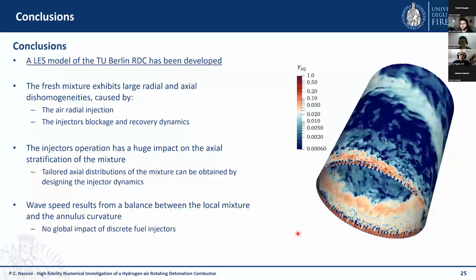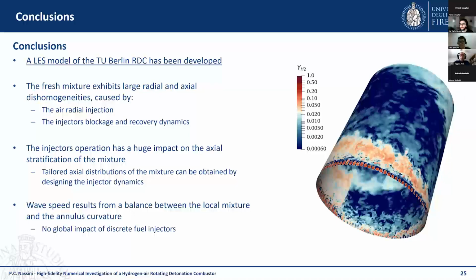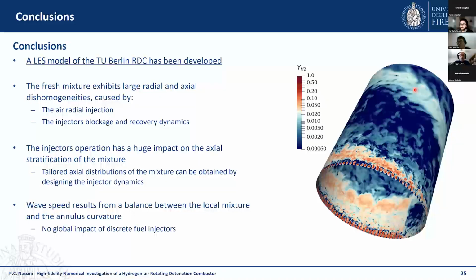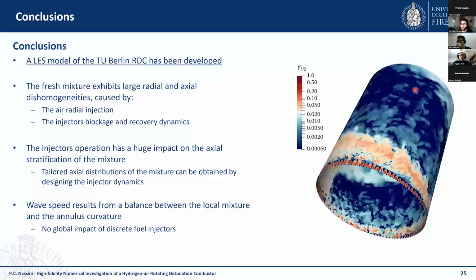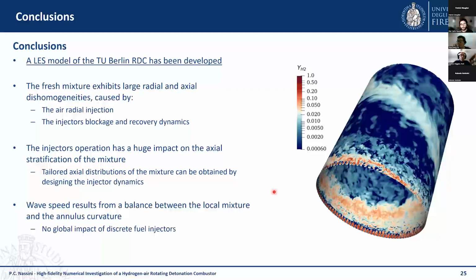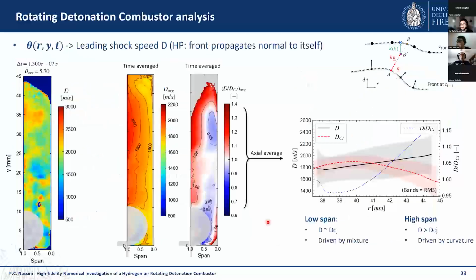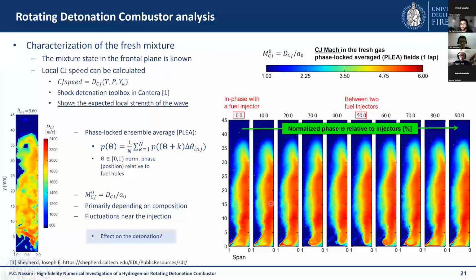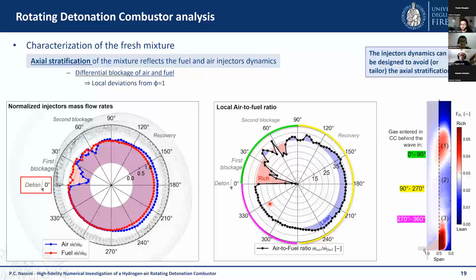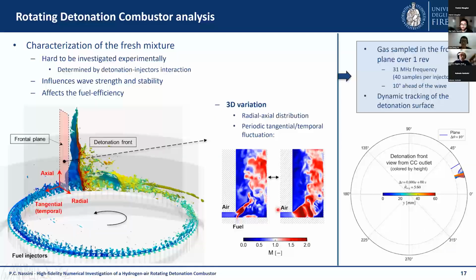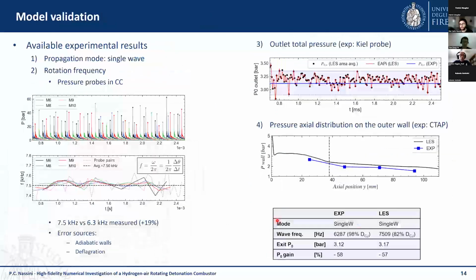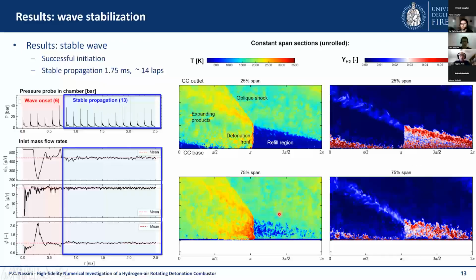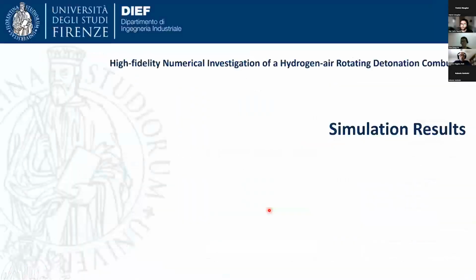Sure, yes. I was a little concerned by a statement that was made in the first sentence of your talk, which was that a detonative combustion in an RDE will result in an increase in total pressure. Total pressure, if you're using the term to mean the stagnation pressure of a flow, does not increase through a detonation wave.